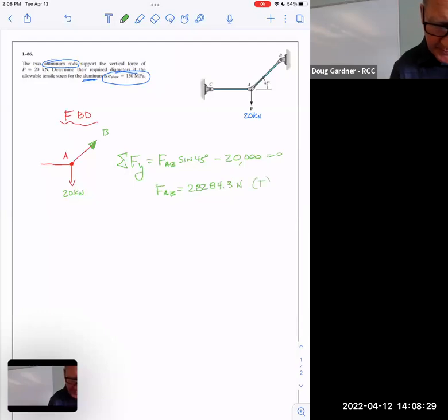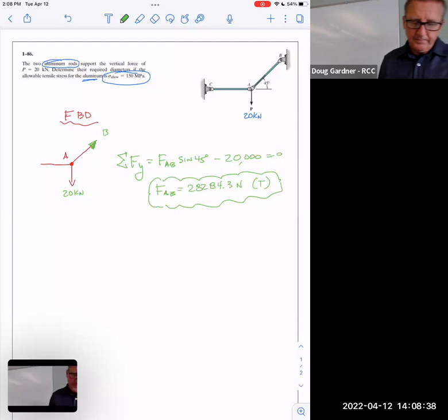And I'm just going to point out, because it's cool, I also know that's in tension. Not to show off, but I already know that. If I had left 20 as kilonewtons, I would have just got 28.3 for that, and that'd be fine too. But it's sitting there in newtons, already ready for my newtons per square meter in case I need it. That's just my growing philosophy. Okay, cool. Am I done? Do I care? Am I finished?